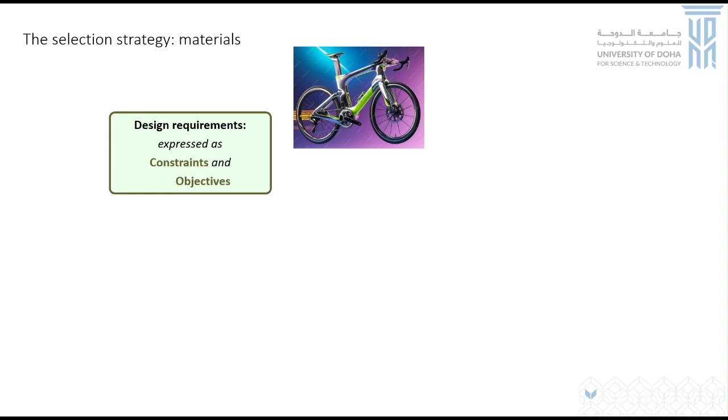Because obviously this bicycle is going to be used by a maximum load. If it's for a child, maybe you'll design it for a maximum of 60, 70 kgs. If it's for an adult, you can design it maybe for 150 kgs. That's the typical maximum load you'll design it for, right? Then if it is being used for mountain biking, maybe you'll consider the impact load as well. So the actual load will go up, because it will be taking those jumps, high jumps and things like that. The effective load will increase, but your initial design load will still be 150. So you'll end up with a fixed constraint on that.